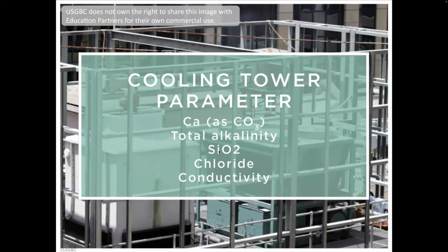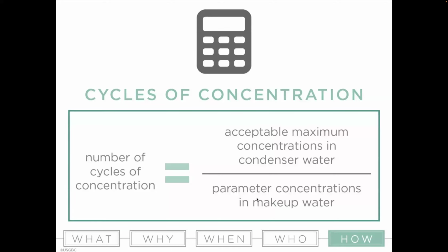And you need to identify that and then find ways you can extend that and treat it. So again, you can find the number of cycles. So the default may be 5 cycles, but you do a water analysis and say, wow, the limiting factor is actually 7 cycles. So you've already increased the cycles just by doing the analysis. Okay. And they call it makeup water. Okay. That water in there is called makeup water.